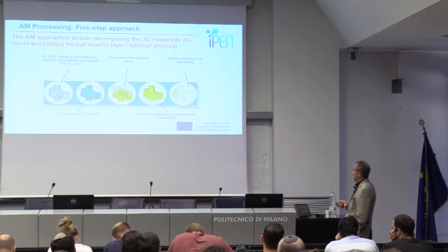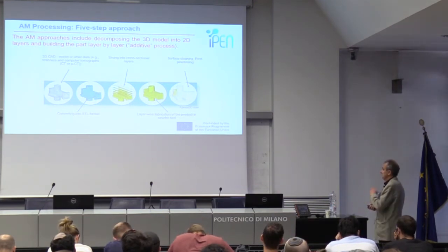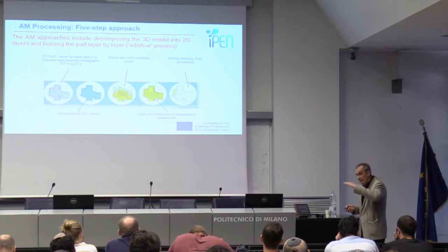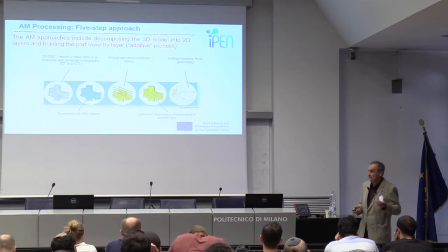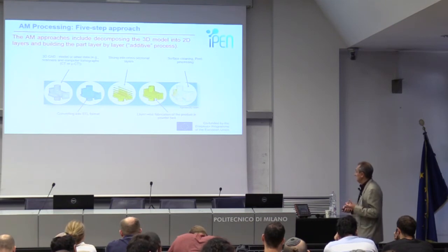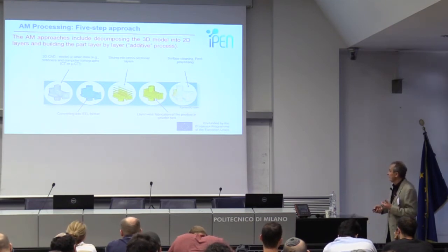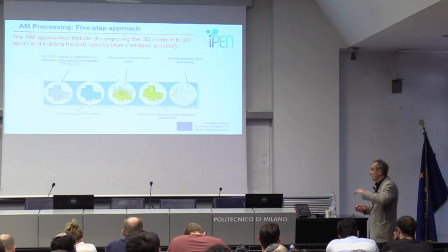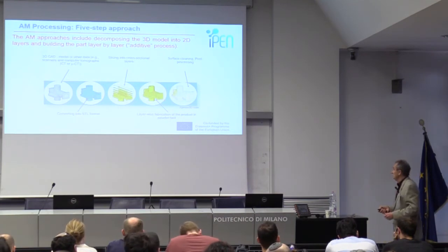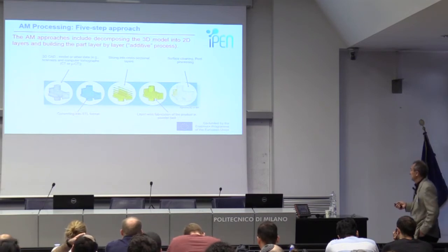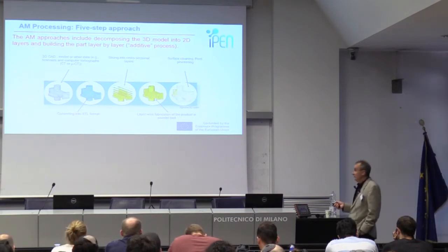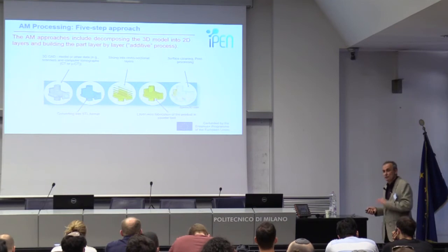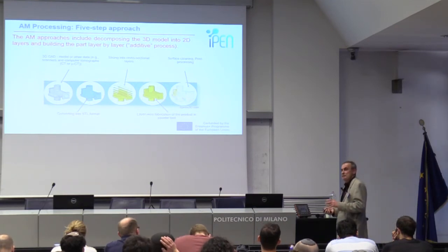After that, you convert it into some format, a computer simulated tomography format. After that, you should make thin slices. Of course, it depends on the process or on precisely what you would like to reach. After that, you can print it layer by layer, exactly your model which you have in your computer. And after that, of course, there is the problem which I mentioned 1 minute ago, cleaning the surface, post-processing. It's not possible to get away from these post-processes if you have this manufacturing technology.